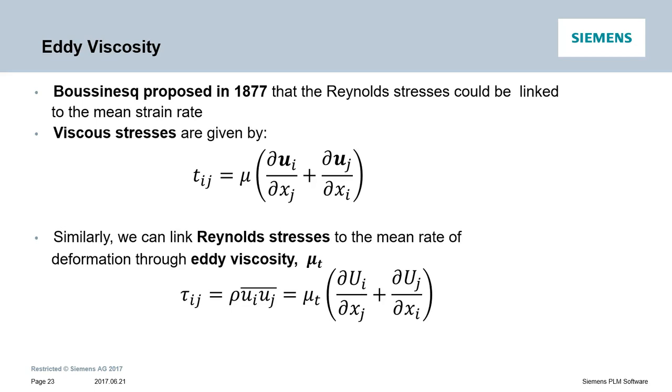And the system is not closed yet, so we have simply pushed the task of determining the Reynolds stresses to now determining eddy viscosity. Now this poor fellow, eddy viscosity, has to tell us the whole story of turbulence, or more precisely, tell the mean flow to behave in a turbulent manner. And so all RANS models of this category, or eddy viscosity models, will try to find a route to estimate eddy viscosity accurately, often through analogy, intuition, and empiricism.